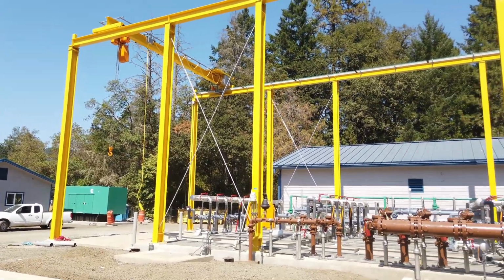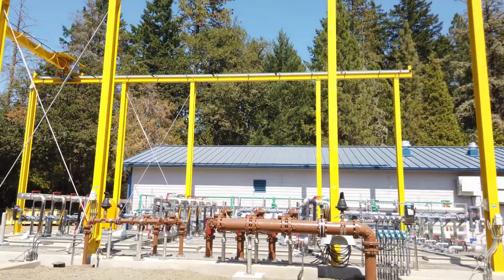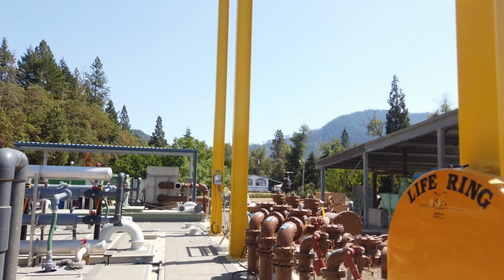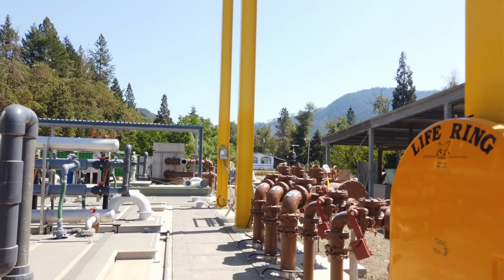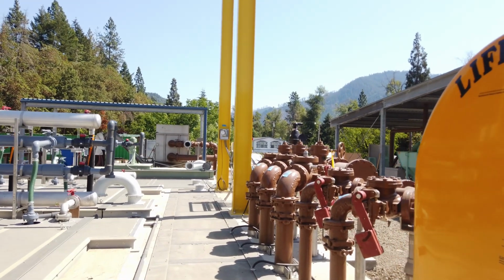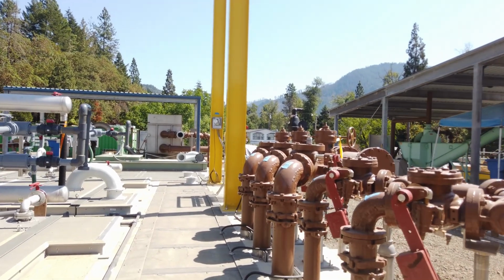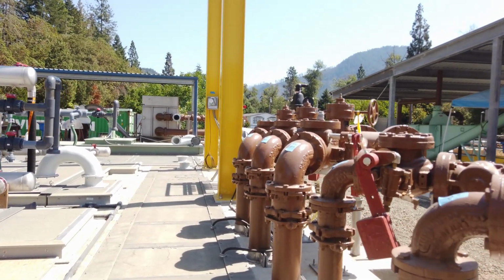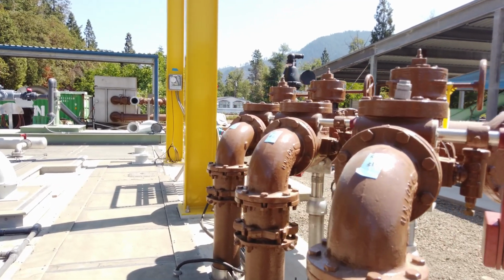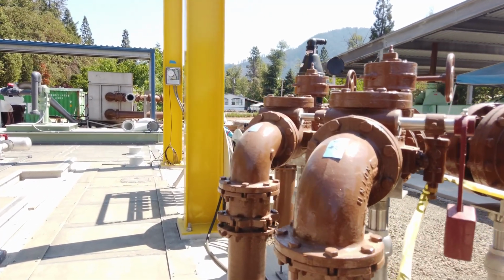There are 2 waste-activated sludge pumps and 3 return-activated sludge pumps, all submersible, centrifugal pumps. The WAS pumps are designed to manage the mixed liquor and convey the sludge to the future aerobic digester. The RAS pumps recirculate highly nitrified mixed liquor to the Anoxic tank for pending denitrification.